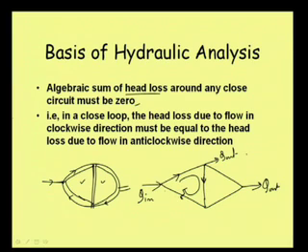Now, if I try to calculate the head loss around this closed loop, then if we sum up the head loss here, HL1 suppose, then HL2, then HL3, if I sum up all the head loss, then we will be getting that from here to here we have some head loss. Now, when we are seeing from the beginning, say at this point we have some head available. Now, if I just go around the loop and reach here, then the head available here will become say H minus HL1 plus HL2 plus say HL3.